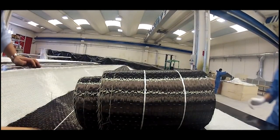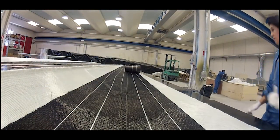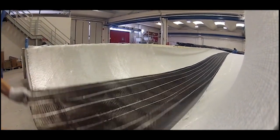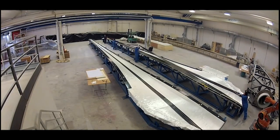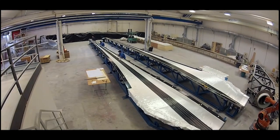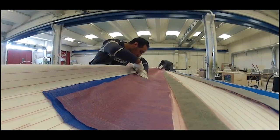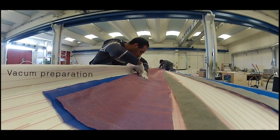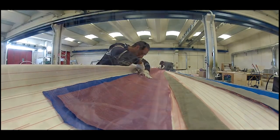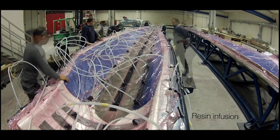Fibers are laid up one layer over the other. Here you see the black of carbon. So first carbon fabric layers are stacked. Other layers of fabric could be prepared, for example, glass, and then vacuum is prepared. You see here the resin infusion, the transfer of resin in the part thanks to the vacuum that is affected over the part.